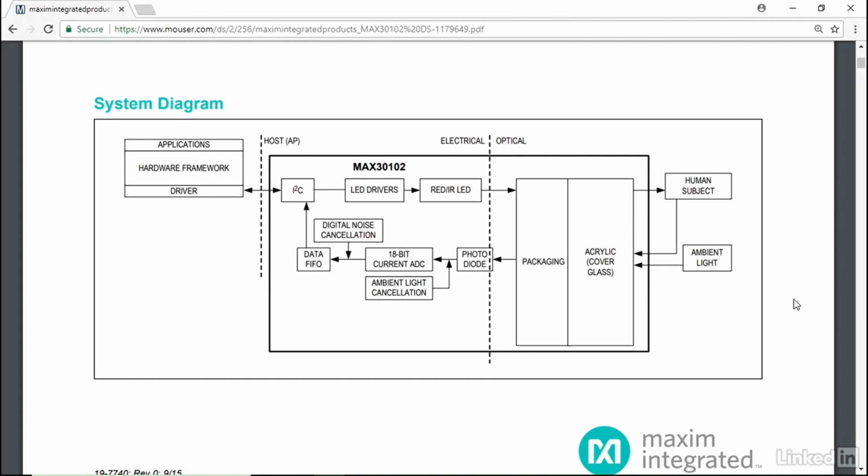Now, let's see how to read the sensing values from your OS-based application. Inside the sensor, there are some registers and data buffers to hold the data for you, so we can read that through the I2C interface through the bus driver. If we read through the I2C interface, we can use the interrupt pin to generate interrupt events to be handled by the ISR. Once that's done, the buffer is cleared and the process can be repeated for new readings.